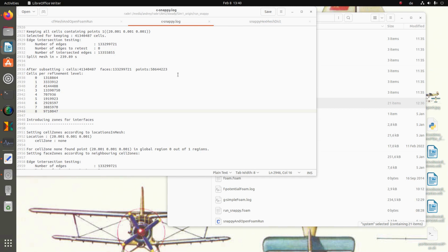Anyhow, later I start the meshing where I set the cell size to 1 millimeter in the area of the cooling grips. If this meshing process runs well, then for me it means that I can model the cooling grips in the original thickness on such an airplane.